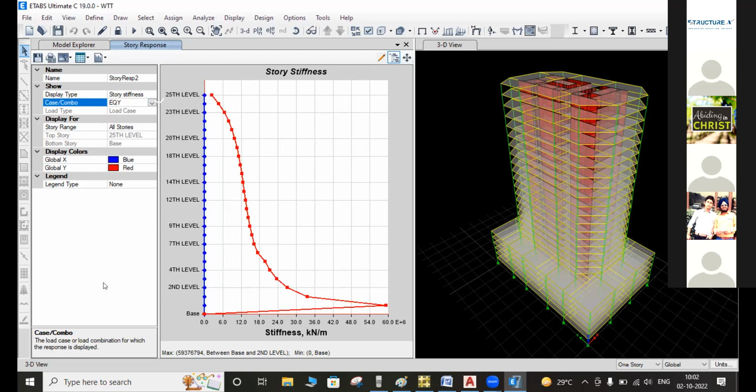When using the Excel sheet, we also identify the soft story, heavy story and mass irregularities. So first of all, we need to see the picture and whether our result is convenient or not. Sometimes the section size of the upper stories becomes stiffer as compared to below, so the story stiffness for the upper becomes higher than below. The member sizes should be taken from bottom to top, high stiffness to less stiffness, because the axial force acting at the bottom is high.